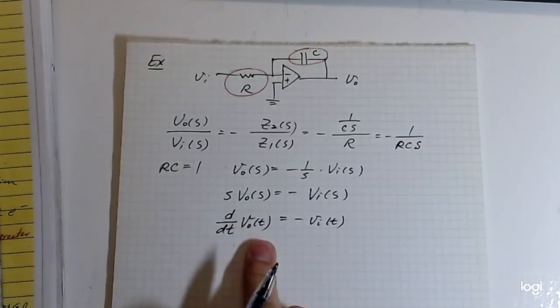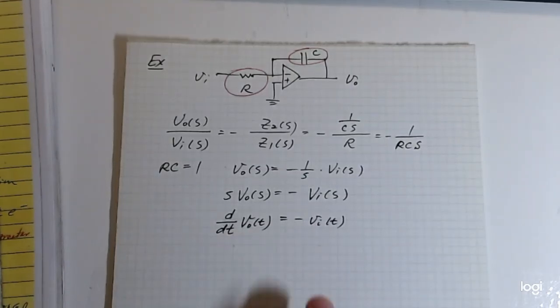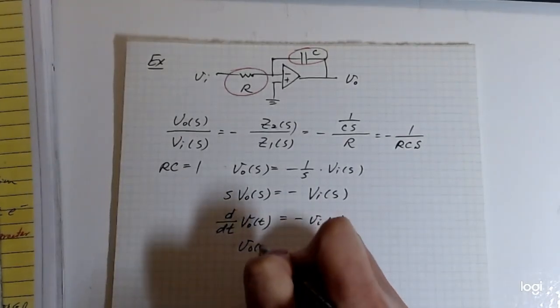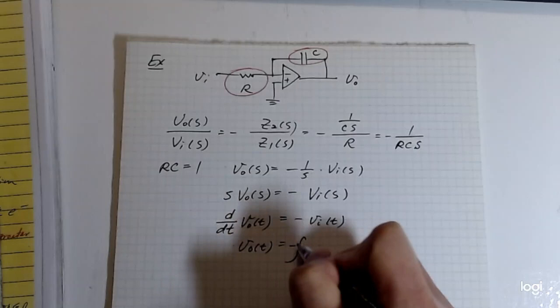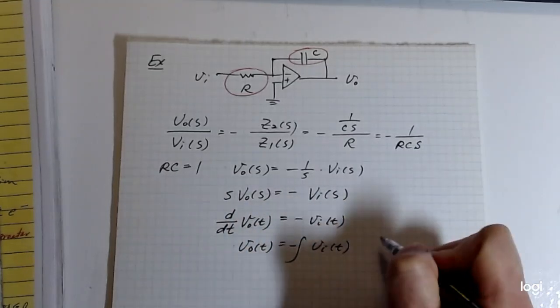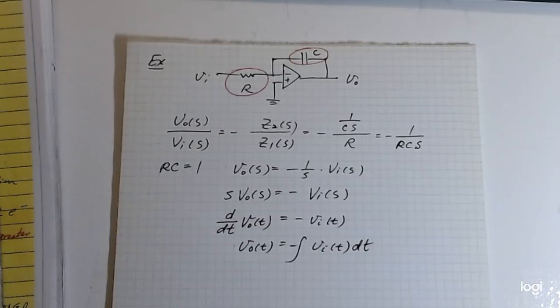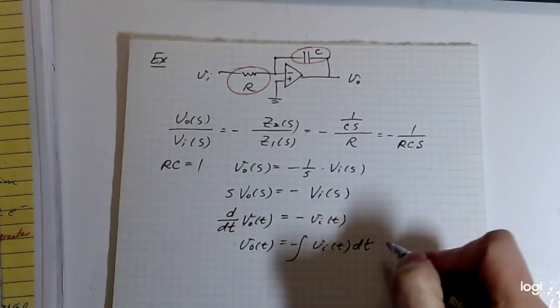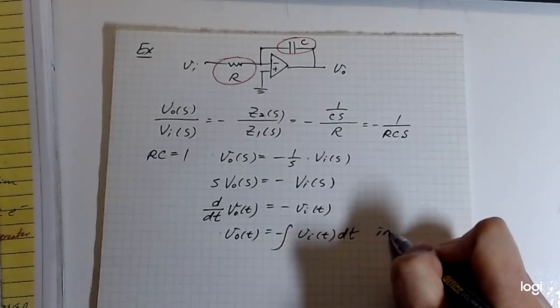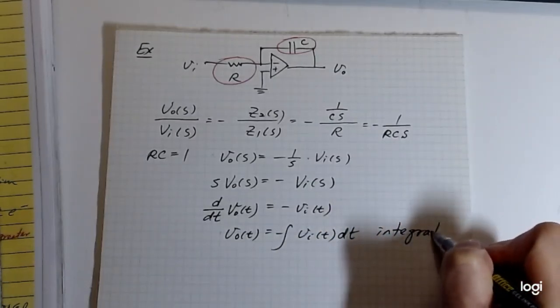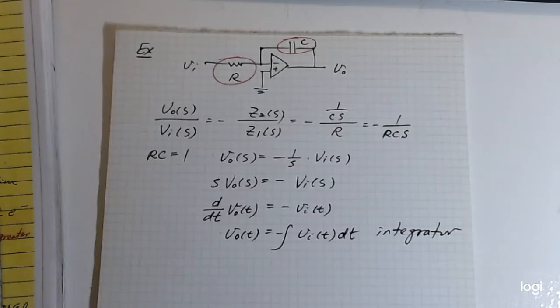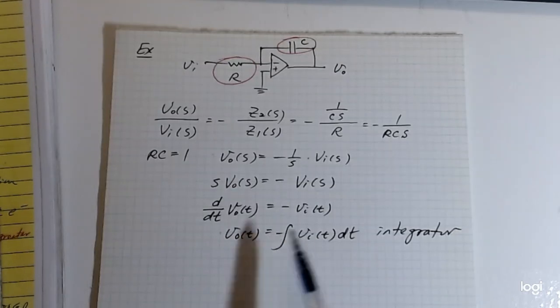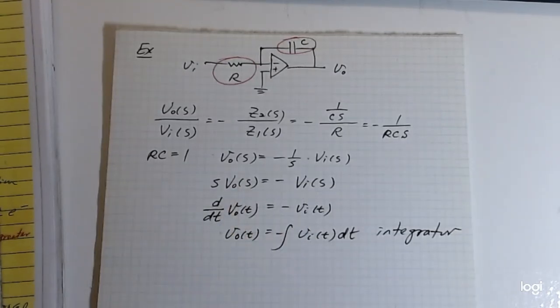In other words, what's VO? So what is this circuit for? Your output will be the integration of the input signal. So this is what we call an integrator. The minus sign can be corrected with another op-amp inverter, so you invert the sign, that's fine.